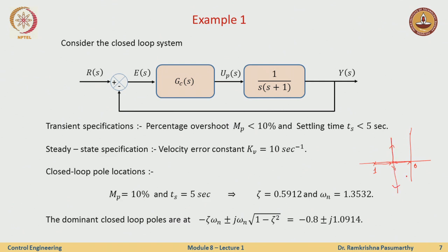Okay. Now, I want my compensator to be such that the closed loop poles or the dominant poles should lie on the root locus. This is what the system is. So, this is the root locus of G of S, I can just say, well, can I just add a controller K, proportional controller, and check if my requirements are met.